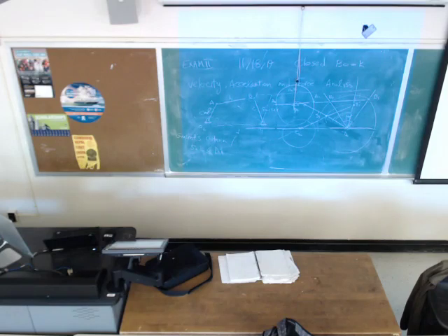The other line has the angle of 45 in this example. Connect B1 to B2, extend, and pick any point, which is going to be the location of O2. Draw a circle with this center and diameter of B1, B2. Then you have O2, A1, B1, O4, which is going to give us our mechanism.